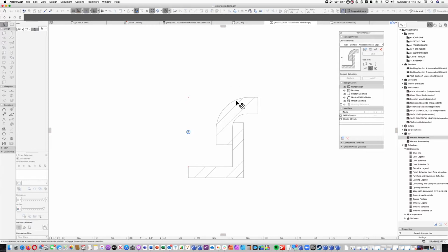I believe I already have it correct in this model, so that's what you're trying to go for, is you're trying to set it to the center point of the glazing, which in this case we're calling the Lignobond panel that's going to be lining up with this, okay? And then I'm only drawing the edges, not the whole panel, because obviously the panels are going to be different sizes, so we want to make sure that we draw this in as a filled region on the profile. This profile I drew in with a radius and then kind of stopped it there.